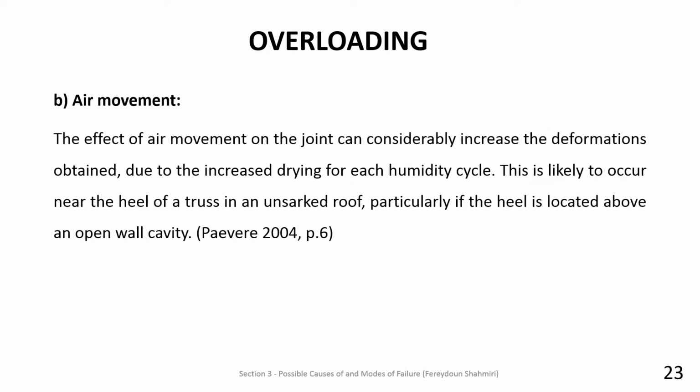Air movement. The effect of air movement on the joint can considerably increase the deformations obtained due to the increased drying for each humidity cycle. This is likely to occur near the heel of a truss in an unsarked roof, particularly if the heel is located above an open wall cavity.